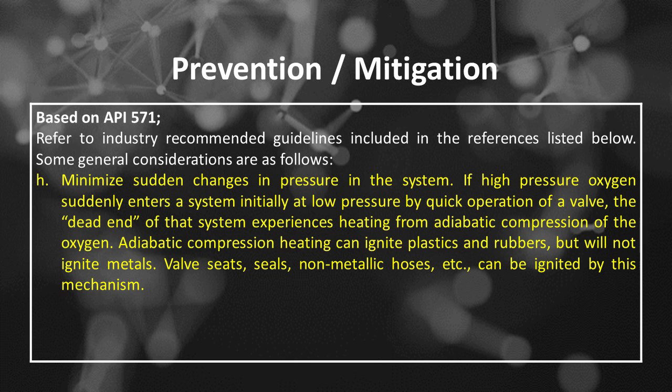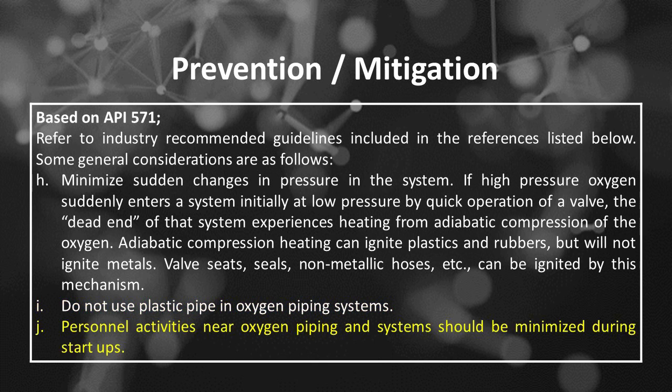If high-pressure oxygen suddenly enters a system initially at low pressure by quick operation of a valve, the dead end of that system experiences heating from adiabatic compression of the oxygen. Adiabatic compression heating can ignite plastics and rubbers, but will not ignite metals. Valve seats, seals, non-metallic hoses, etc., can be ignited by this mechanism. Number I, do not use plastic pipe in oxygen piping systems. Number J, personnel activities near oxygen piping and systems should be minimized during startups.